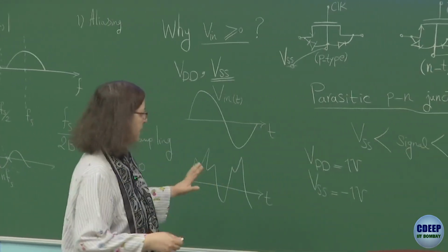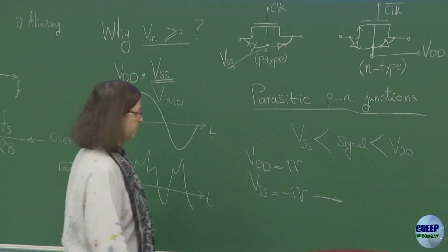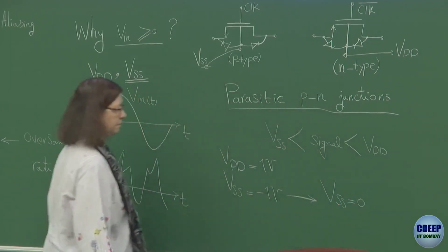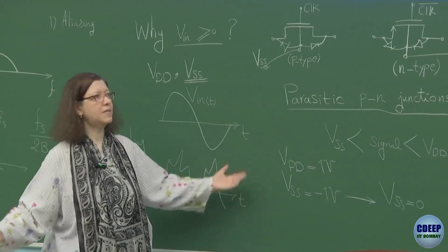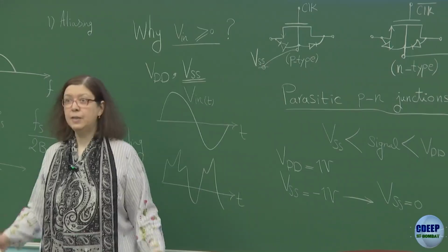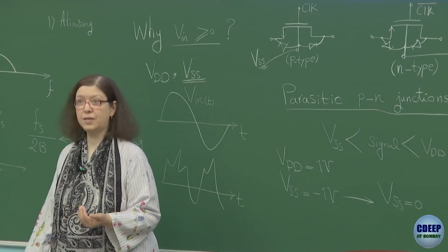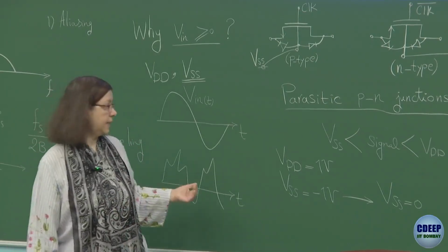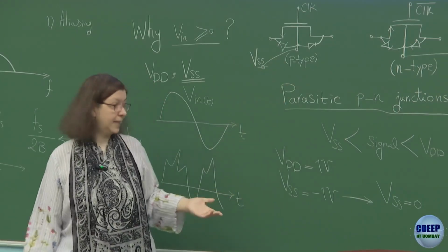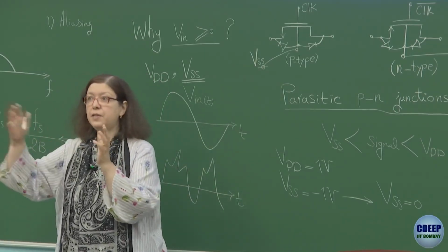So therefore, the best thing to take care of everything across all designs, all integrated circuits which are designed, is to keep the VSS a standard value of 0. Now, all systems will be synchronized. Eventually, they will not have any problem. What is the implication? It says that you cannot apply negative signals directly to these systems unless in your design you are very careful about the situations that you have. Or you can later, at the boundary, have a circuit which eventually converts everything to a 0 reference signal.